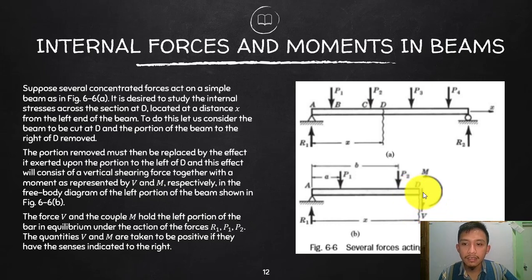which is what we call the shear. Again, this is just to expose the internal forces and moments. So what is the reason why there is a moment and shear here? Actually, that represents the effect of the other side of our beam. So if you want to analyze this beam by cutting at a section, all you need to do is put back the effect of the other part that you removed.